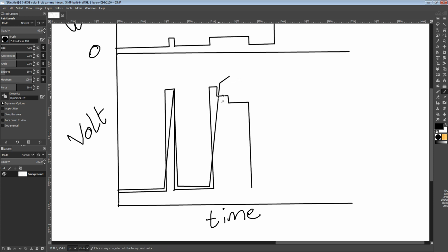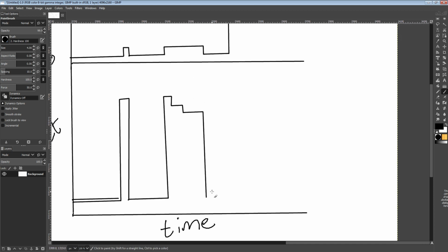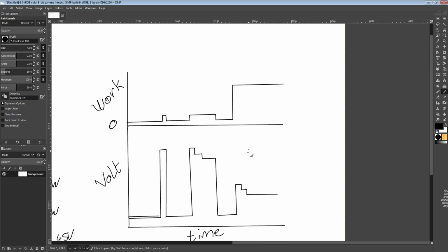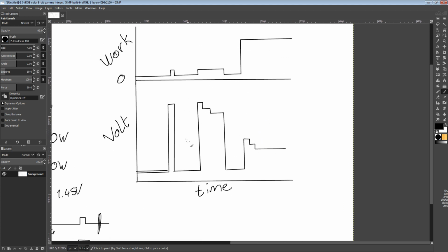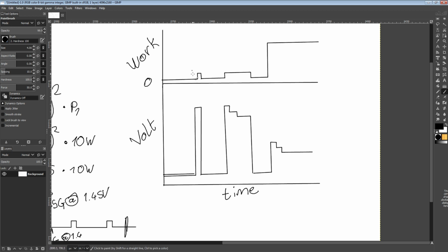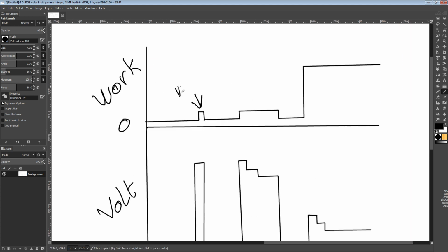And the chip would be like, oh, wait a minute, and it would start lowering the frequency and lowering the voltage to get the temperature under control. And then when you hit an all-core workload, it'll actually also boost up initially quite a bit, and then it'll sort of settle down to a long-term safe voltage. So it also behaves kind of like this, which is why, when you move the mouse, like this is mouse moving, the algorithm basically freaks out and gives you that.